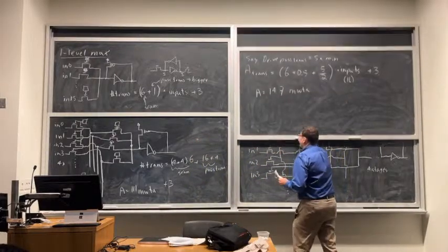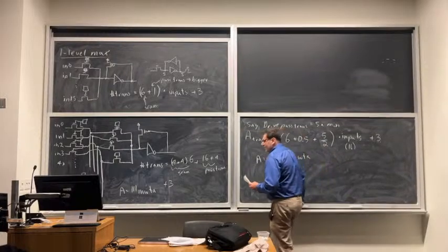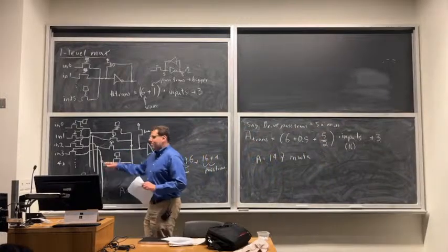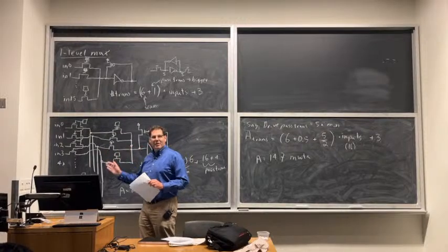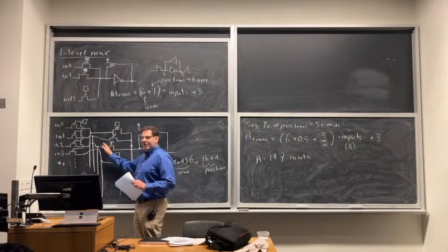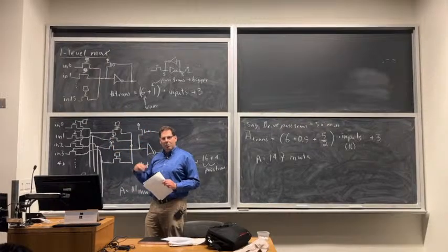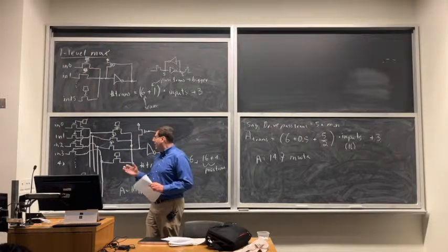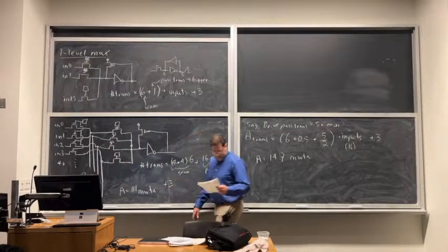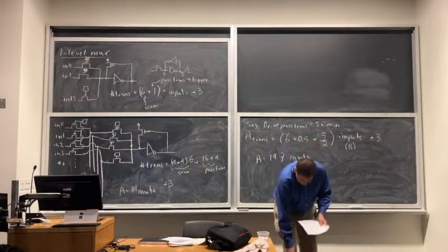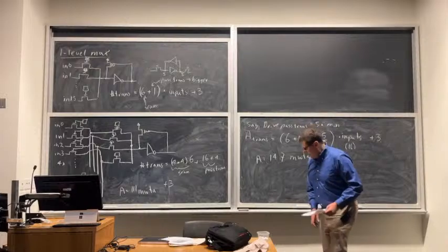And we use routing muxes like this all over an FPGA, so that's why it's useful to think about how you build this. This is kind of the dominant design. So for really small muxes, like 4-to-1 and so on, 1 level mux makes sense. As you get into bigger muxes, usually 2-level is the best. Okay, so the other thing we need to look at.